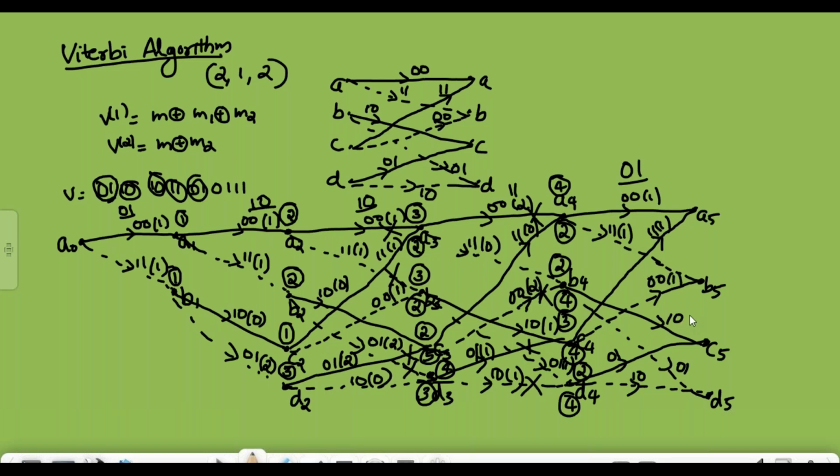This we have written associated with each branch. We are writing the branch metric. Okay. Then we will have to write the path metric here, total path metric. So here 2 is the metric, path metric, total path metric up to this node A4. Therefore 2 plus 1, 3 here. Then another, here we have 3 up to this 3. Then 3 plus 1, 4.